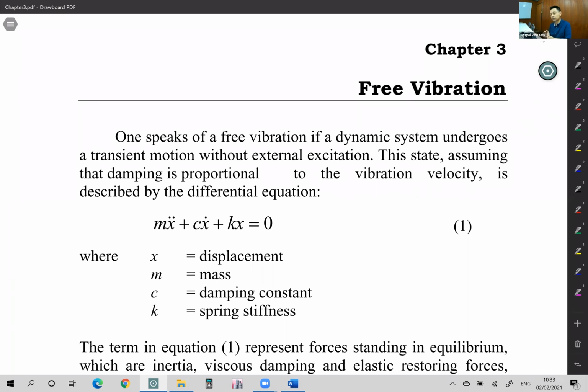Before you formulate, you have to make what we call the physical modeling: find a way to model your actual building by putting a mass on each floor, connected by springs or stiffness, so that this physical model represents your actual building motion under wind, earthquake, or any excitations.